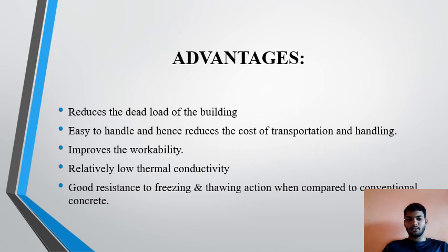Then advantages: reduces the load of the building, easy to handle and hence reduces the cost of transportation of the building, improves workability, relatively low thermal conductivity, and good resistance to freezing and thawing action when compared to conventional concrete.